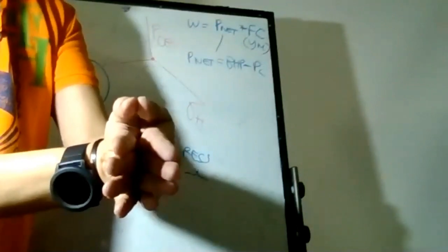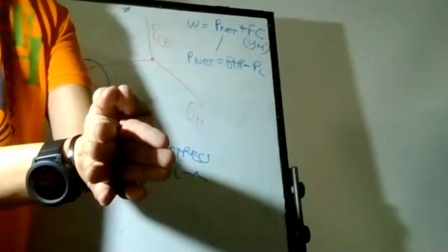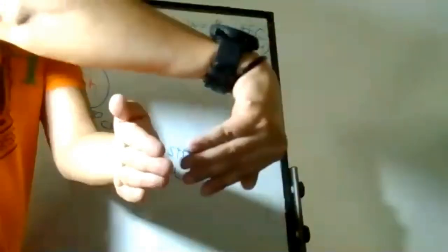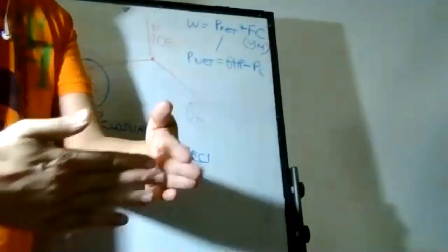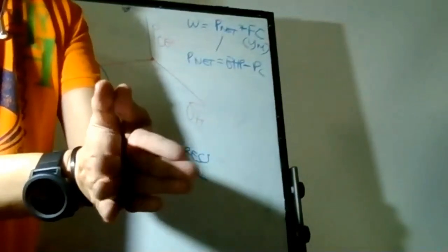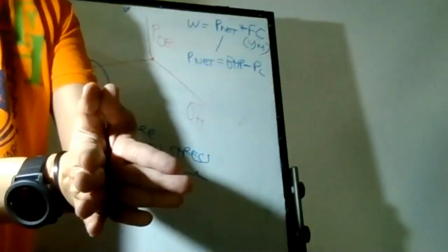It starts to crack, and you start developing the width. This is your width against the minimum in situ stress, because your width can only open when it fights against your minimum in situ stress, not the maximum one.